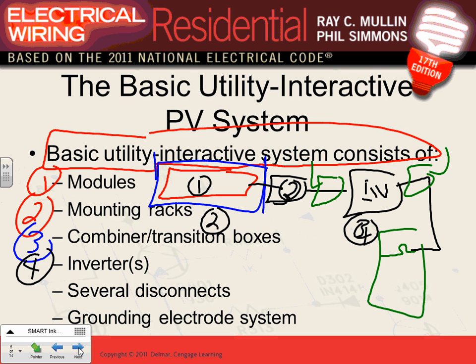You are looking at a solar photovoltaic system: a panel to a combiner box. From the combiner, you disconnect it. From the disconnect, you go to an inverter. Up here, you can have up to 600 volt DC. On this side, in dwellings, they go to 240/120. Any questions, guys, about this? These are the major components.